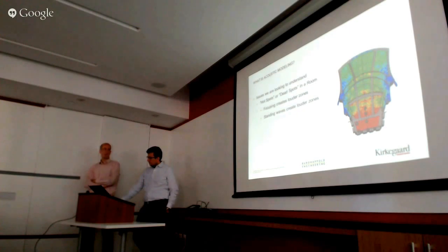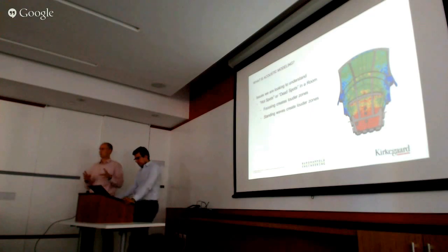And the other, more complicated concept would be hotspots or dead spots in the room. And that could be caused by geometries that tend to send sound to one specific seating area and not others. So in a larger room, you can get areas where it's really loud in some areas and other areas don't get the same level of envelopment. And then in smaller rooms, it can actually just be because the sound wave itself is so physically large compared to the dimensions of the room that the sound pressure is going to build up in some areas and not in others.